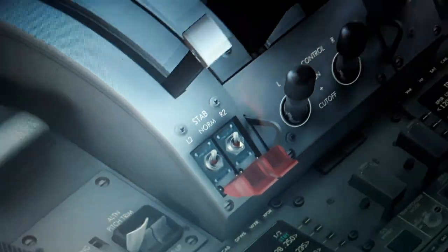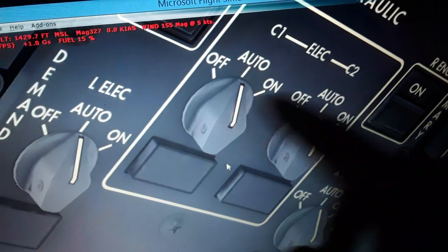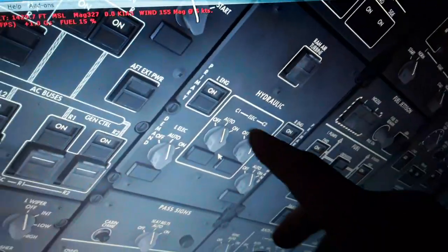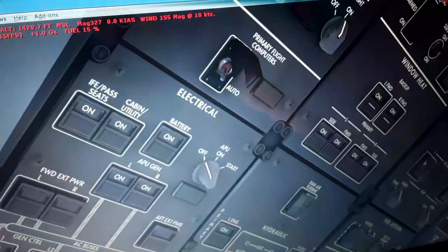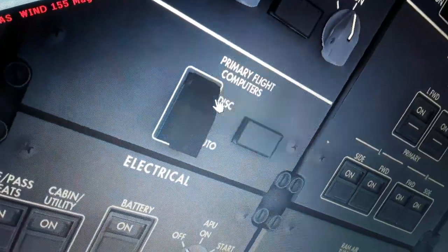So we have a failure of the flight hydraulic systems over here of the Boeing aircraft that affects either left horizontal or right horizontal stabilizer movement and elevator movement. We have the flight control computers over here. We're gonna lose the automatic trimming, because also this is a fly-by-wire aircraft, like the Airbus has the automatic trim, the auto trim system. As we fly, it can trim the horizontal tail itself automatically. So we're gonna lose the auto trim from the Boeing 787, and we have a failure of the hydraulic systems, as you can see also.